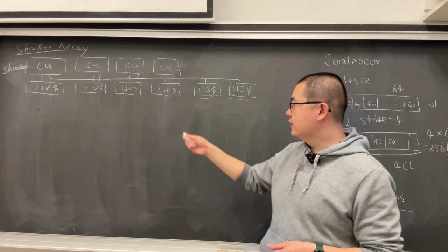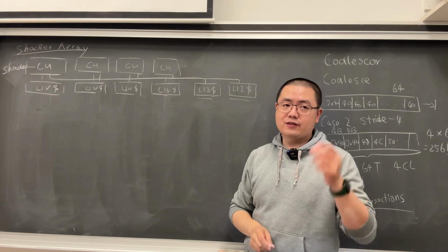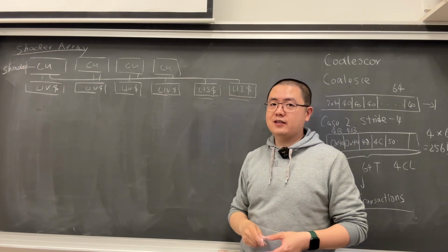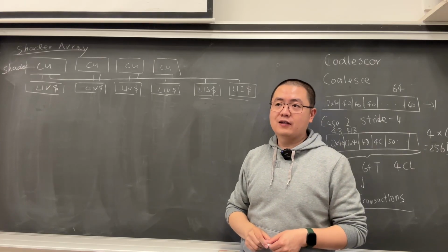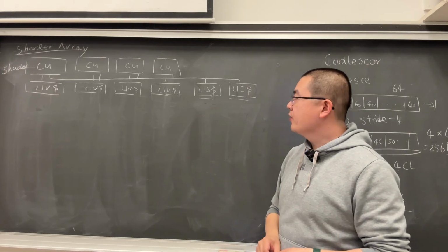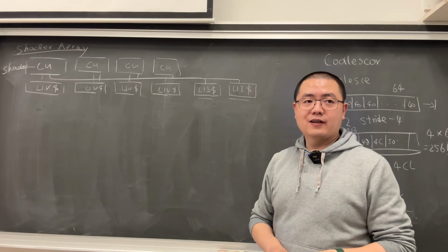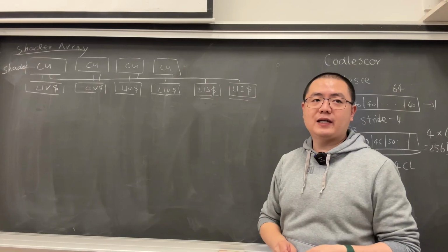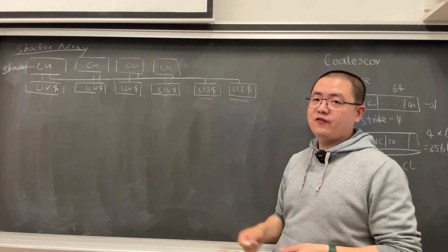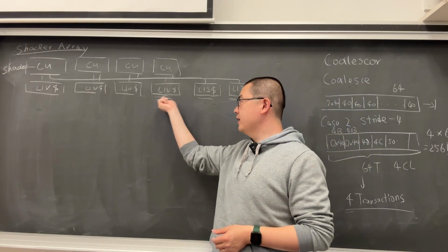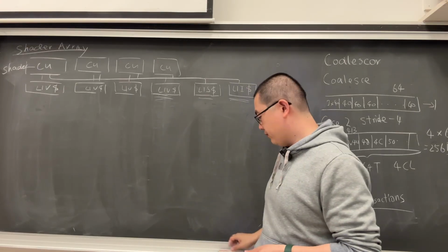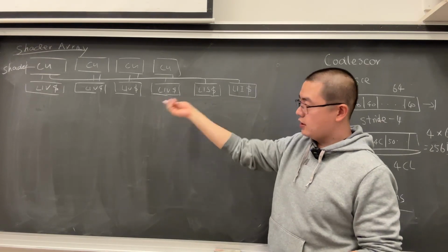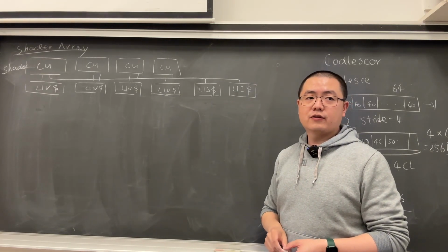Another very common question, in a CPU, is this: when you have a data cache and an instruction cache, an interviewer may ask you why you need 2 caches. The always right answer is they have different locality. They have different access patterns, right? For example, this one we are very likely to hit, while the cache hit rate here is actually quite low. But anyway, those are the L1 caches and L2 caches.